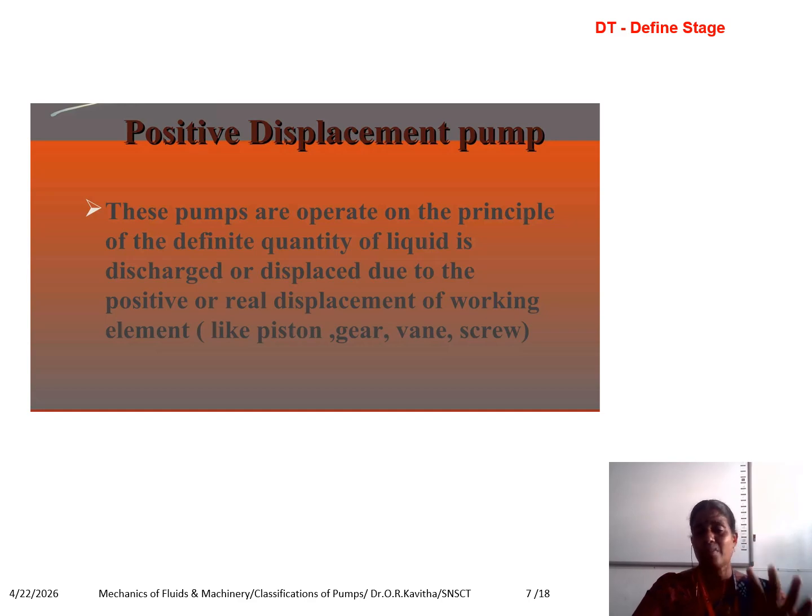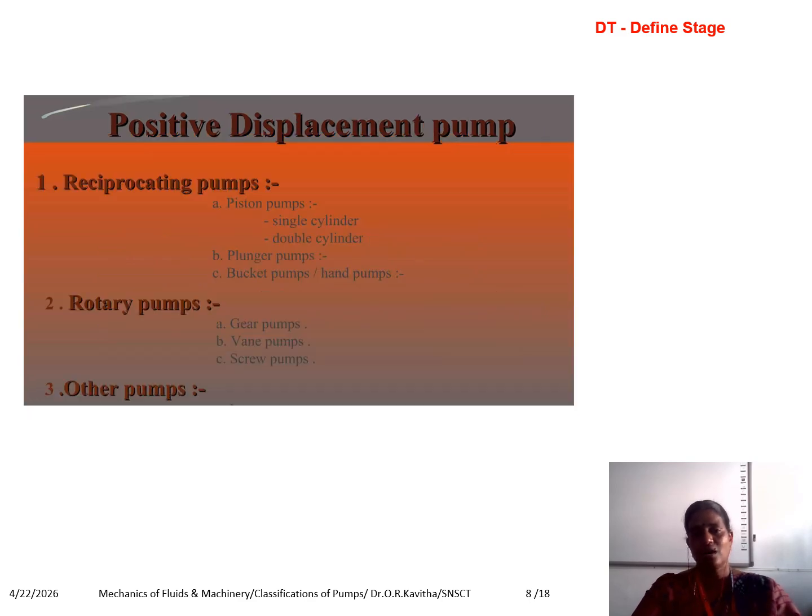In a positive displacement pump, a fixed quantity of liquid is discharged due to the positive displacement of a working element, which may be a piston, a gear, or a vane. The main classifications are reciprocating pumps, rotary pumps, and other pumps.